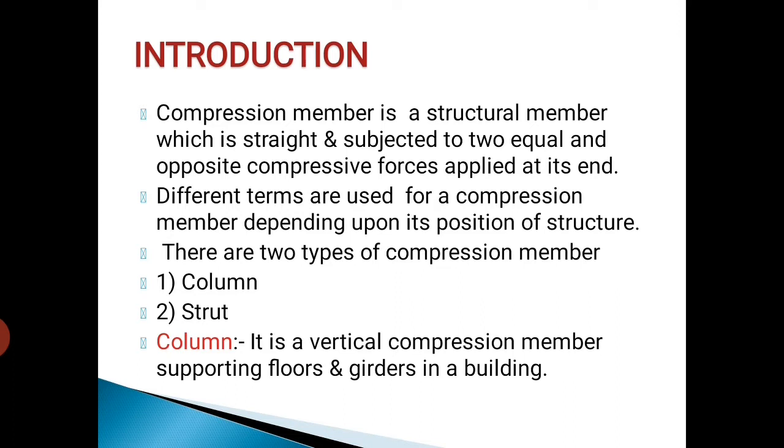How to decide? Under the axial or compressive loads, a member deflects in a direction perpendicular to that of load. Then deflection occurs along the weaker of the two axes of the section. Some examples of compression member: column, strut, post and top chords of trusses.